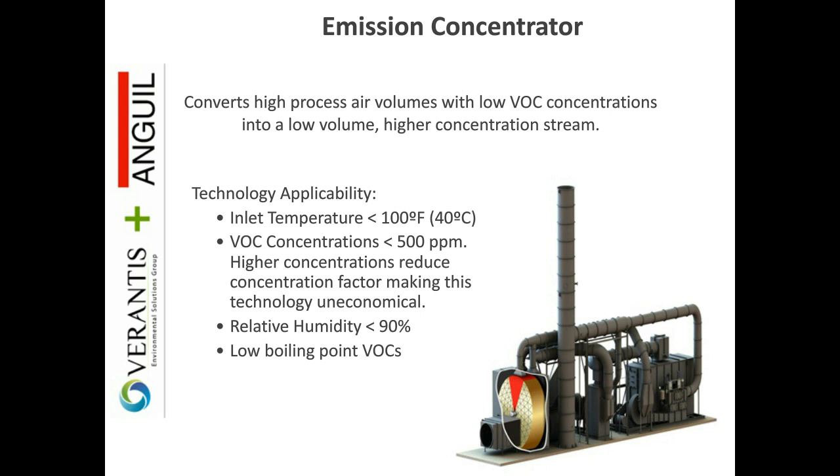So really where you see these applied, if you can imagine what it takes to paint an airplane, you can't put a close capture hood over an airplane, so you're basically evacuating a hangar. So you're looking at potentially hundreds of thousands of CFM with very, very little solvent in the airstream. That's where this would be applied.